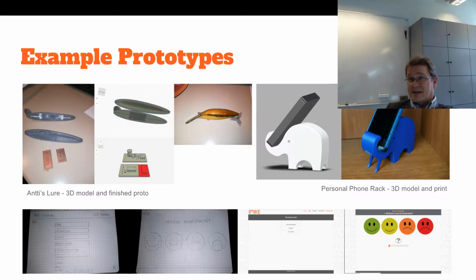Then designing that second generation prototype, which is 3D printed in plastic, took something like 3 hours for the plastic part. About 2 hours to do the electronics part. We also have devices here to make PC boards, or printed circuit boards, and it takes about 1 hour to produce those circuit boards, maybe half an hour to put the components on. So in total, using these modern tools cut down the prototyping from 2 weeks to 1 day. It's doable in 1 day.